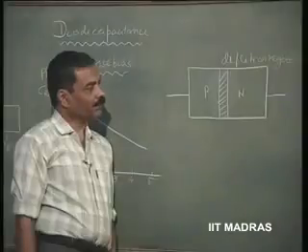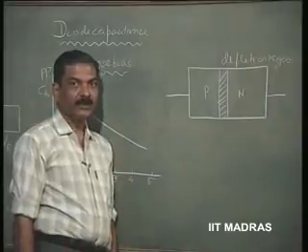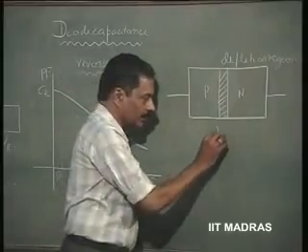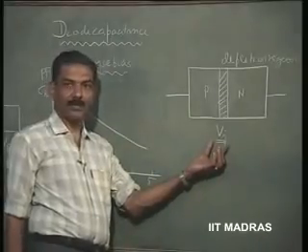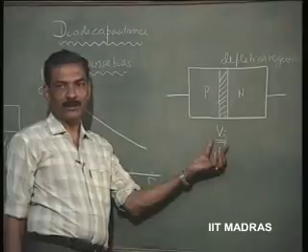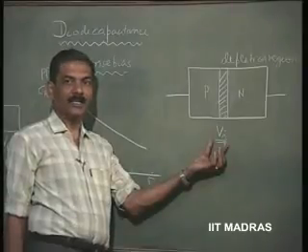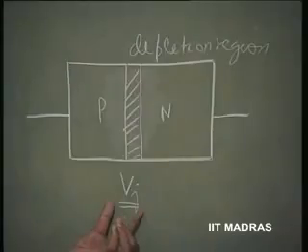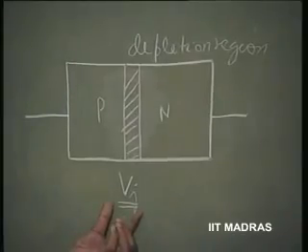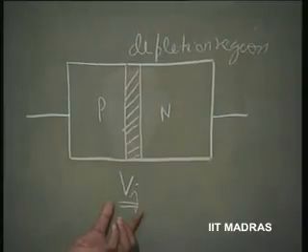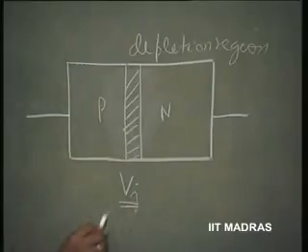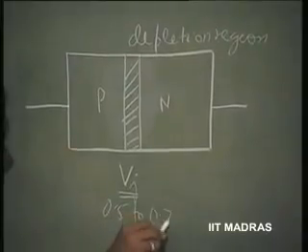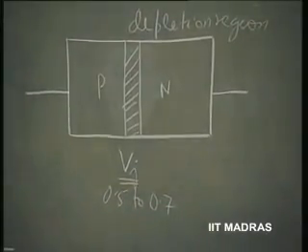Thereby it develops a potential hill. This is called the junction potential, V junction. And this V junction, according to the semiconductor theory, for silicon happens to be around 0.5 to 0.7 volts, we said. That is why the semiconductor diode was not exactly close to the ideal diode. There is a deviation from it. It starts conducting only when a junction potential of about 0.5 to 0.7 volts is applied. Then the current is unlimited. Until that time, current is negligible.